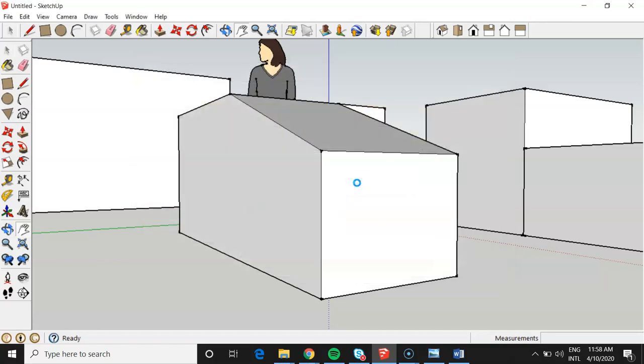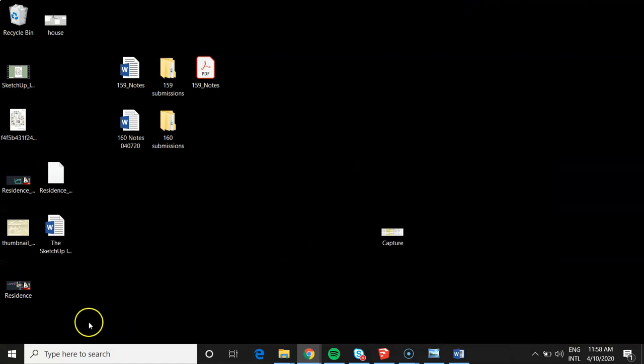Yes, we'll replace that. And now we want to open that file up in Photoshop and change the resolution to 220. Changing the pixels to 4,000 makes it a bigger file, but it doesn't necessarily set it to 220. So it's probably, I believe, if I recall, the default, it's going to go back to 72 resolution and be a really big image, kind of like they come off our camera at school. So you want to change it to 220 and then let the size of that image shrink. Okay? All right, so that is the kind of bare bones intro to SketchUp. All right, good luck with it.